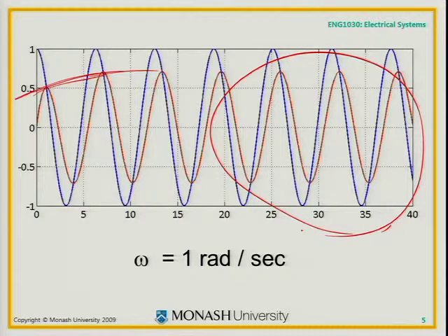And what do you notice about the frequency of those, the red and the blue? It's the same. Nothing we do in terms of having different resistors, capacitors, inductors can change the frequency of the input. Linear operations don't change frequency. You can differentiate a sinusoid, another sinusoid of the same frequency. Multiply it by a scalar, add things together. You can't change the frequency with linear operations. You would need nonlinear operations like diodes to introduce other frequency components. So if we've got one frequency source, every other voltage and current is going to be the same frequency. And so we can see that there.